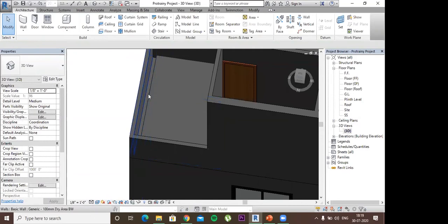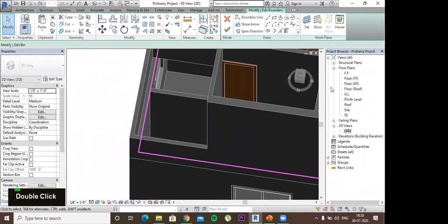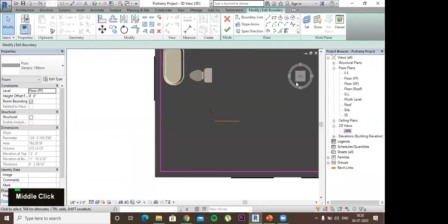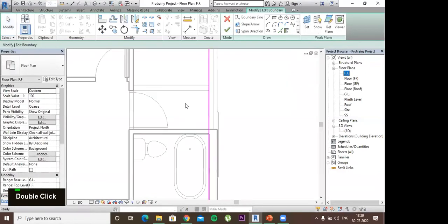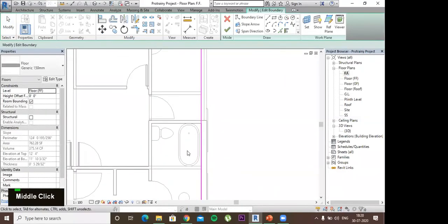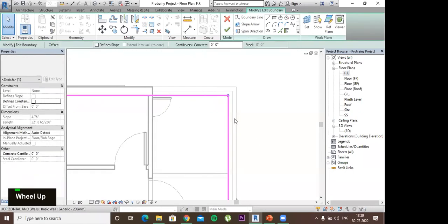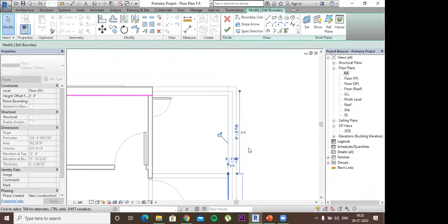So what we can do is, in these type of situations, when your wall width is actually less than the outer wall, then you can select the floor, go to the top view, or you can go to the first floor if this is better in visibility, and select the wall, and you can again make the boundaries from where you want them to be.